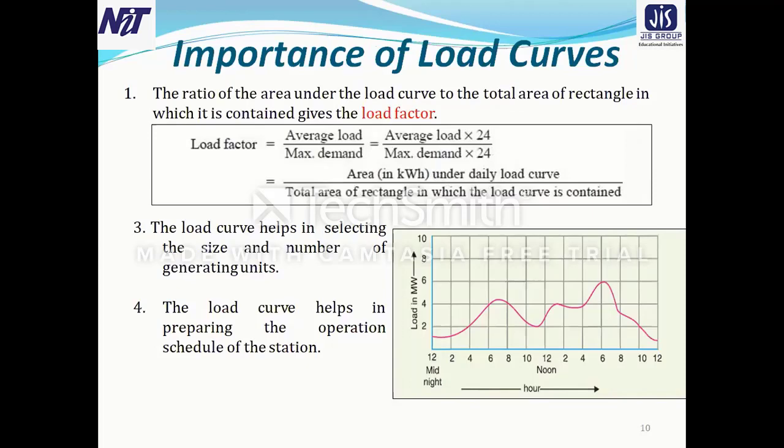You have to remember the definition of load factor. The load factor is the ratio of average load to maximum demand. Here, average load into 24 hours by maximum demand into 24 hours. In this way we can represent the load factor.